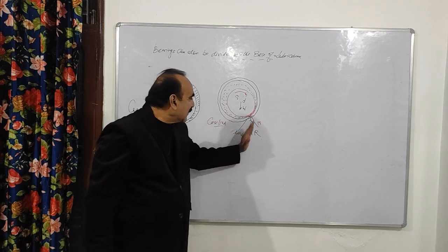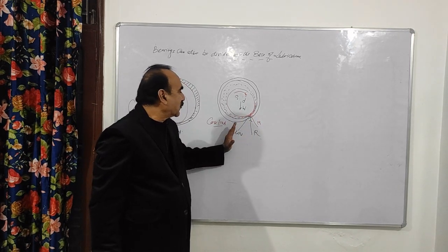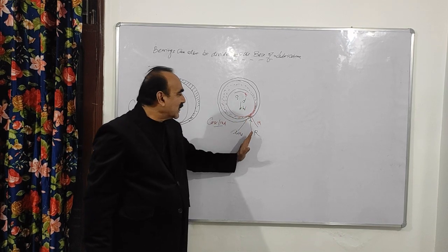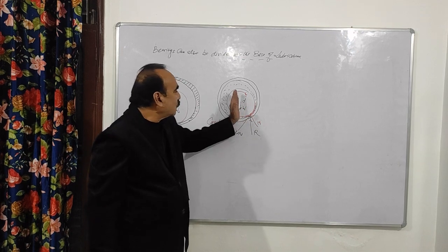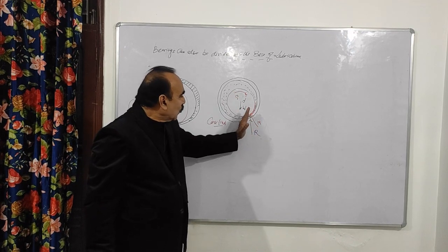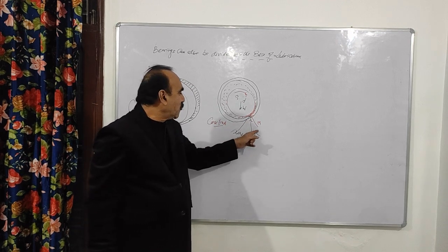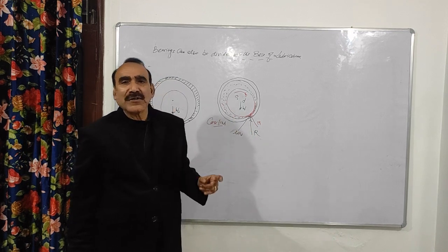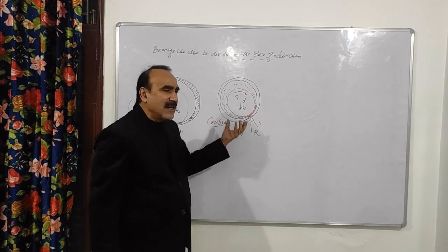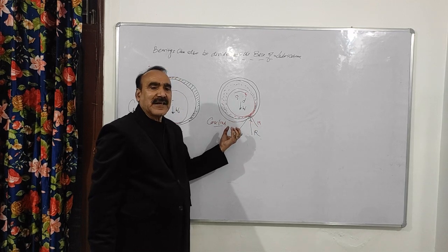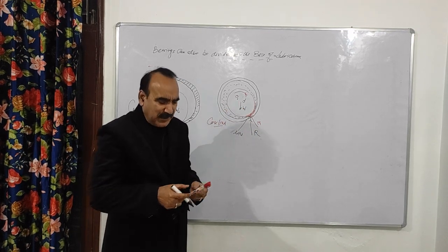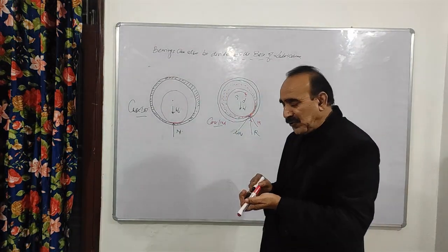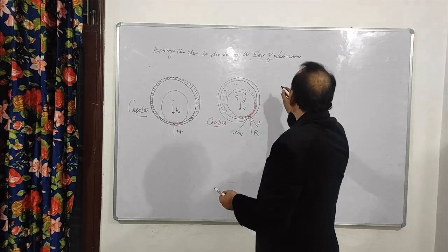So the resultant of the normal force and the frictional force, that resultant force is acting upward, its direction is upward because it has to support the load here. So that resultant of the normal force and the frictional force will support the load. So in the second case, the resultant force acting between these two will support the load. Now we come to the third case, when it is operating at full speed. So that is case number third.